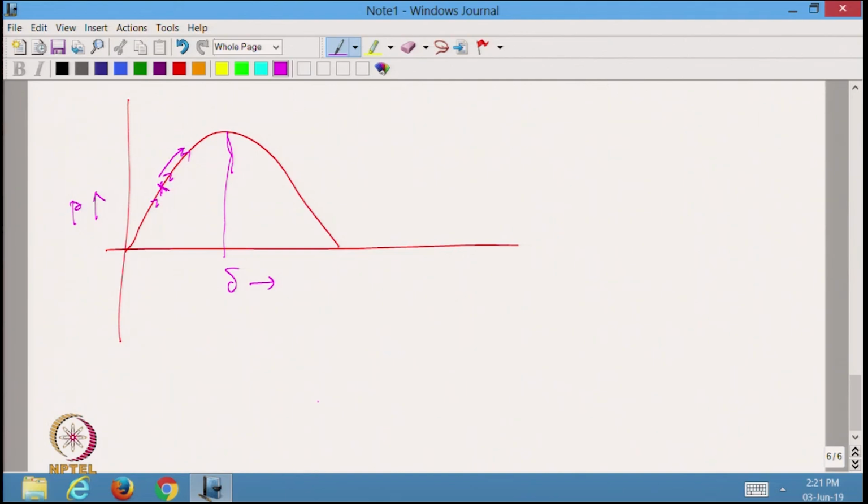Okay. Now, the angle delta is increasing further and further because 1500 minus 1490 RPM multiplied by T is delta, and as time progresses I am going to have an increase in delta further and further.